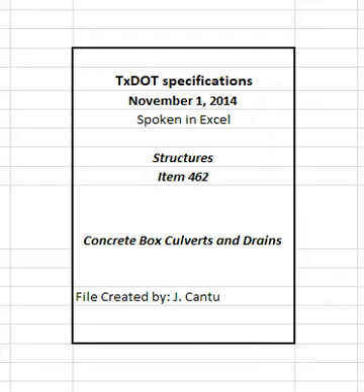2.2.3 Machine-made precast. Machine-made precast box culvert fabrication plans must be approved in accordance with DMS 7310, reinforced concrete pipe and machine-made precast concrete box culvert fabrication and plant qualification. The department's MPL shows approved machine-made precast box culvert plans. Fabricate machine-made precast boxes in accordance with DMS 7310, reinforced concrete pipe and machine-made precast concrete box culvert fabrication and plant qualification.